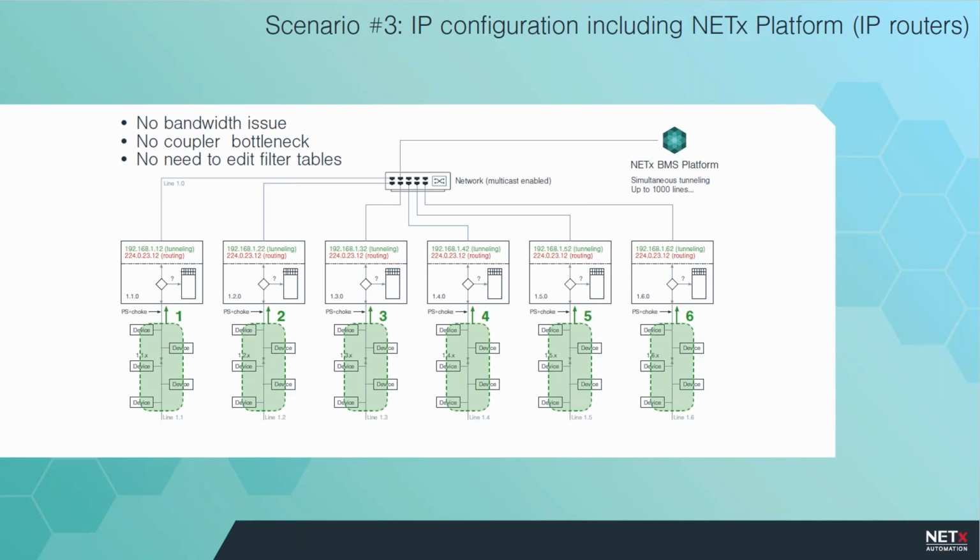every single line with an independent tunneling connection. Very reliable and very professional, because we will have a server connected to the whole installation, to every data point of the installation. And I will demonstrate how easy it is to do this. We call this the mapping of the variables of the data points. Data points for KNX are the group addresses.